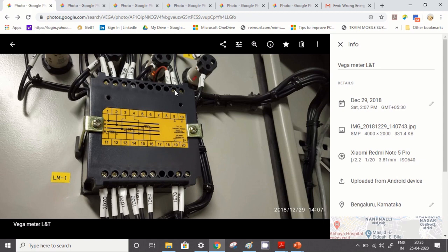So this is also very much required. The energy meter OEM manual mentions that this voltage value can be between 0.5 to 5 volts or so, but there are no specific values, they have just mentioned the range. So we have to check this value with the connection and without connection in the EV meter as well as in the DG meter. By comparison we will come to know which meter's RS485 port is healthy and which meter's RS485 is faulty.